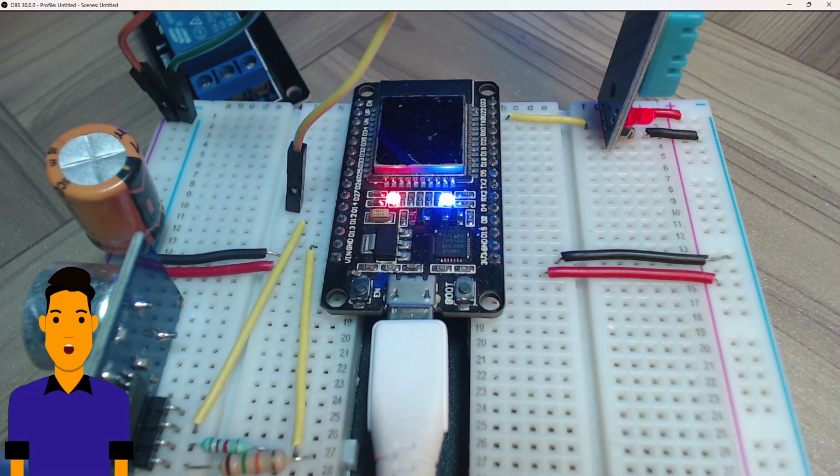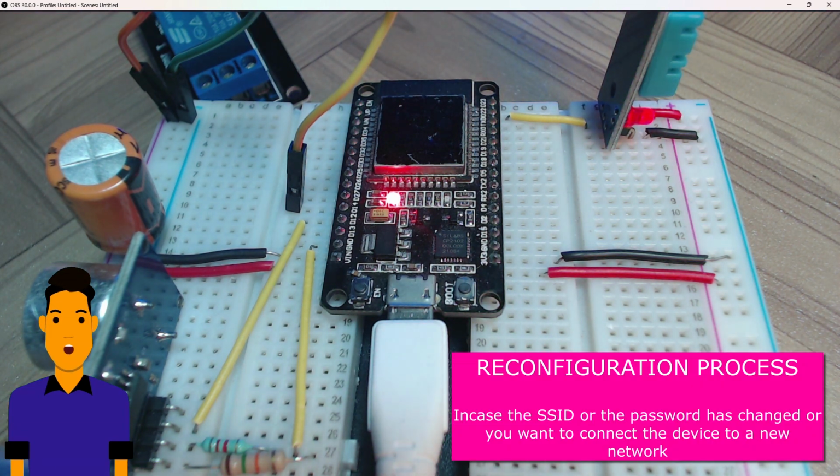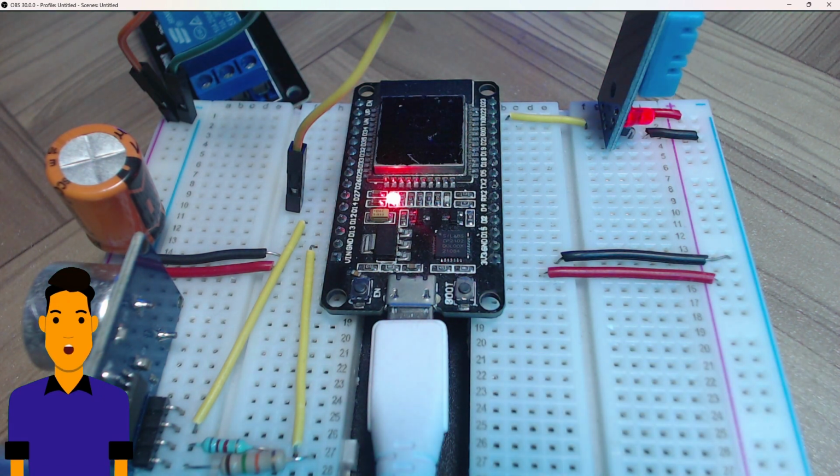Now, there's one last thing that I want you to be aware of. If you already have configured your device with SSID and the password, and later on your SSID or the password changes and you want to reconfigure it, then there is also a way to manually force your ESP32 to get into configuration mode. For that, all you have to do is reboot the device twice. For the very first time, you reboot the device and wait for the blue LED to blink fast, and then you reboot it again. Doing that, it will make it enter into the configuration mode.